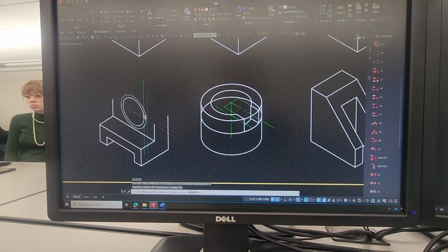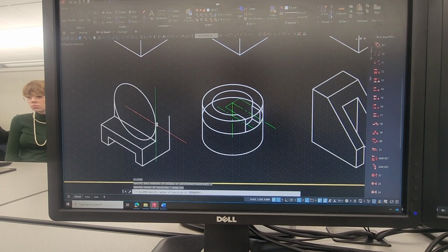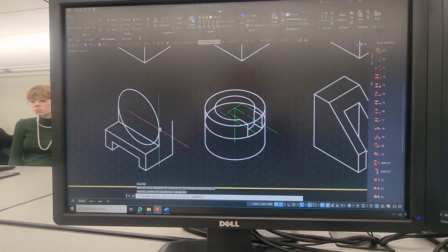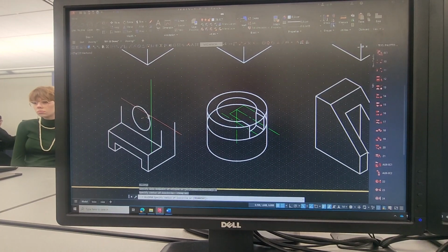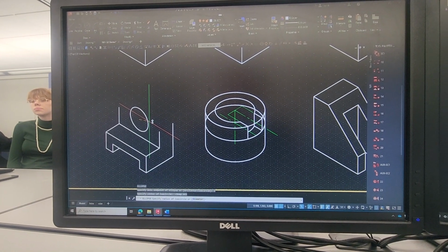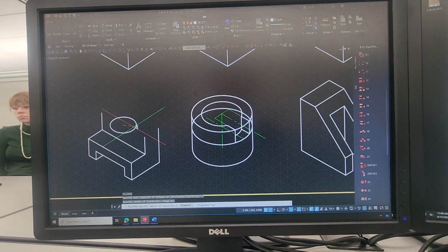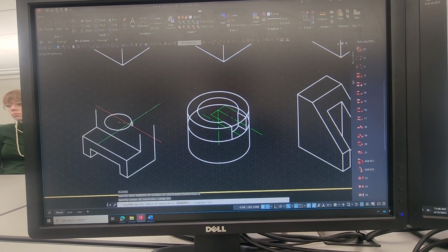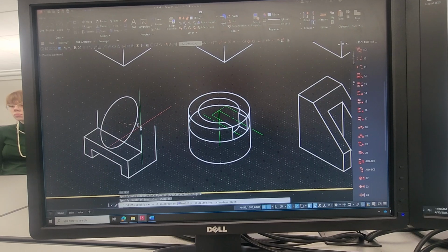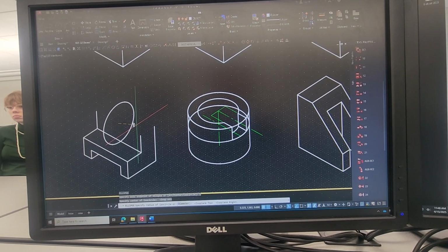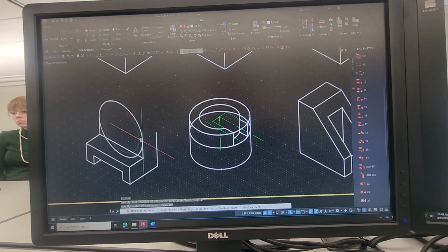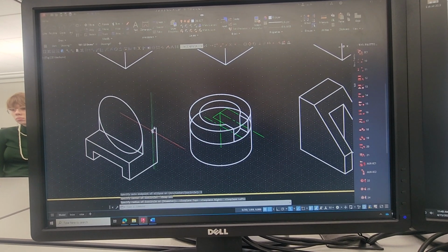Notice what I get now when I'm in that orientation. I actually get an isocircle that gives me the shape I'm looking for based upon the two endpoints. Now, to answer your question about that F5, look, if I change my orientation, now I'm looking at it from the top. Change it again, now I'm looking at it from the right. Does that make sense? So this is where it really matters which orientation you have that ISO set to. So I'm going to go back to the original and simply click on that location right there.